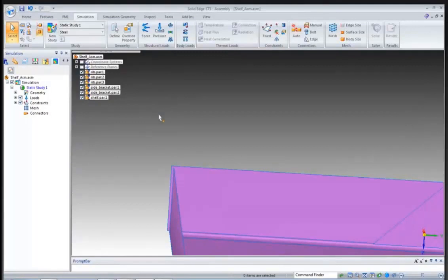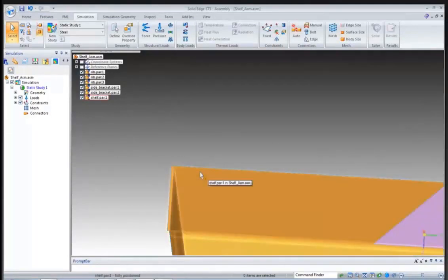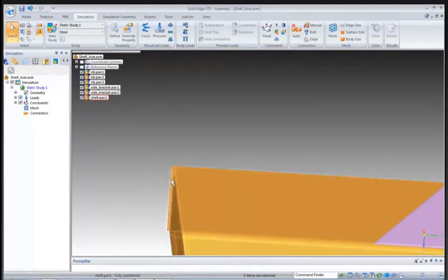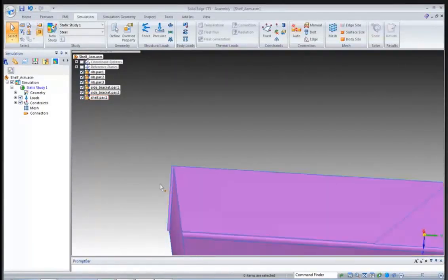So if I had an edge connection, what I would do, and I guess I should explain that because these are mid surfaces, my part was originally 1.5 millimeters thick. Well, now this mid surface is in the middle, so it's 0.75 away from the edge of the surface where the 3D surface used to be. And similarly, this one is 0.575 away, because it's a mid surface. So they're not touching anymore.